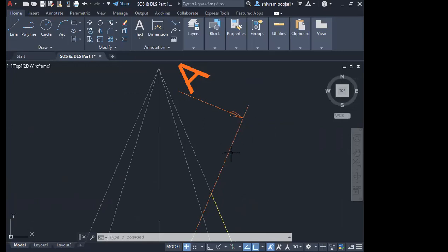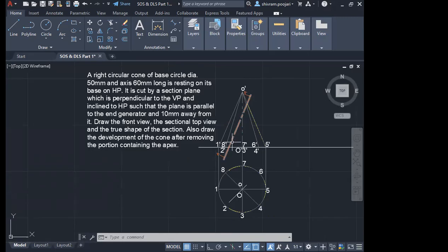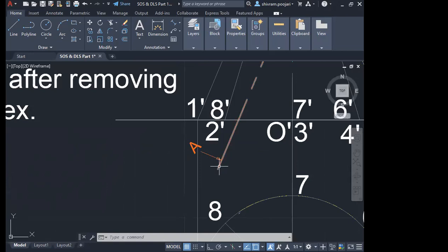Everyone, this is the section line, and the section line has its ends a little thicker. Make only the ends a little thick, not the whole line. So the little end you have to make thicker. The thing you are doing here, do the same here as well. If the two ends of a line are thicker, that means it is a section line.